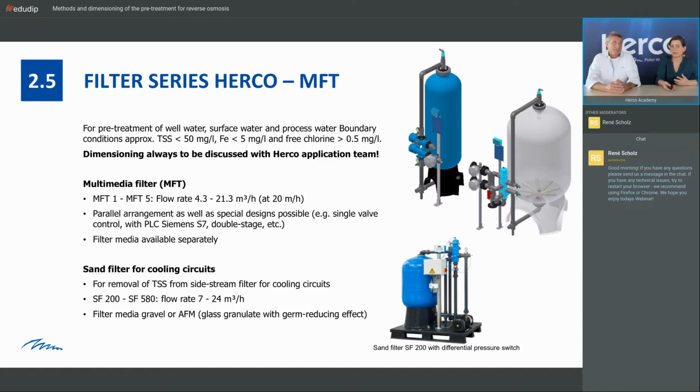Yeah, exactly. And when you have very, very short times for the filter run, in the end you use a lot more water for the backwash. At some point it's the same water that you put in, right? Yeah, but sometimes you have no alternative. You have only this well water, or you have only this kind of water. You don't have city water, tap water in your region, and then you have to live with this. But then you have to build up strategies which enable that.